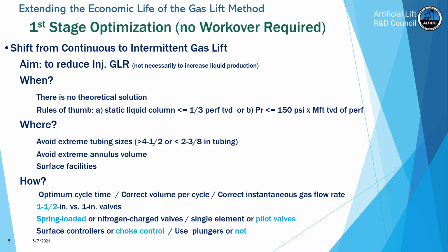So when we do the calculation, the theoretical area ratio that we need once we finish the calculation might be lower than the one that is commercially available. And that's very bad because we're going to end up over-injecting the well per cycle, which is precisely what we don't want. Now, one of the things that we can do here is to lower the opening calibration pressure of the valve, because the spread of the valve is also proportional to its opening pressure.